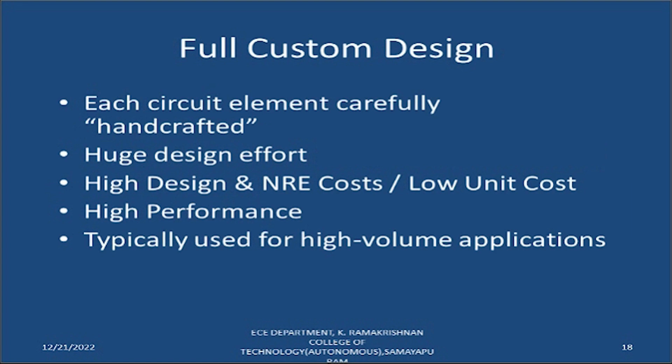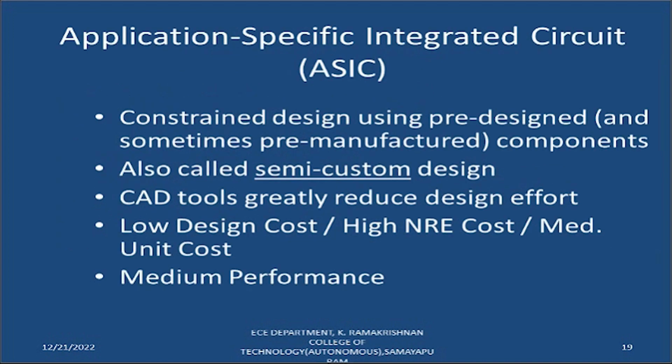If you take a full custom design, each circuit element will be carefully handcrafted, and the design effort should be more. Because we are designing the circuit ourselves, more care is needed. And if the design effort is higher, the non-recurring cost will also be considerable, and unit cost should be low, and that depends only on the design engineer. And here the performance should be high, and this is especially used for high volume applications.